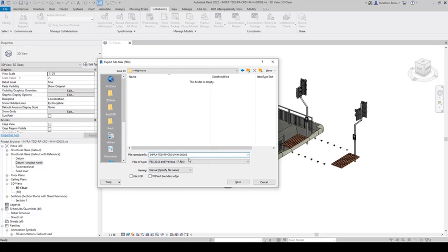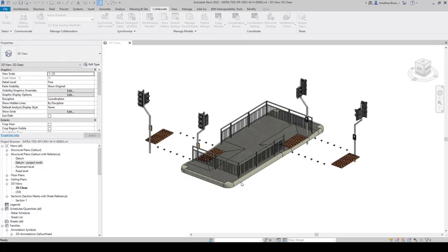If we import a Revit model, it is live linked and can be easily updated as and when it is progressed. It also mitigates the need for further files to be created. Alternatively, the FBX file is frozen in time but is more lightweight, aiding in navigational performance and better aesthetically, as the Revit materials will be exported as is.